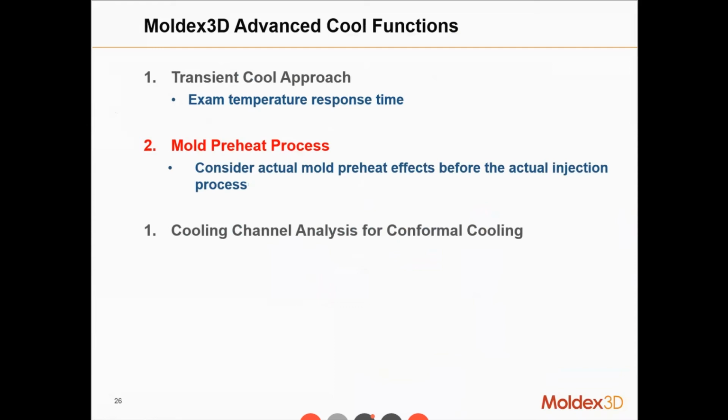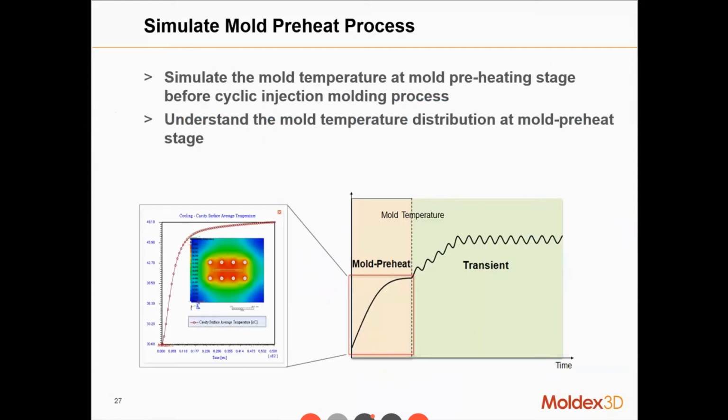The other one is mold preheat. We consider actual mold preheat effects before the actual injection process. In practice, molders will do the mold preheat. So this function shows you the temperature distribution inside the mold and also the progression of the temperature, such as this chart.